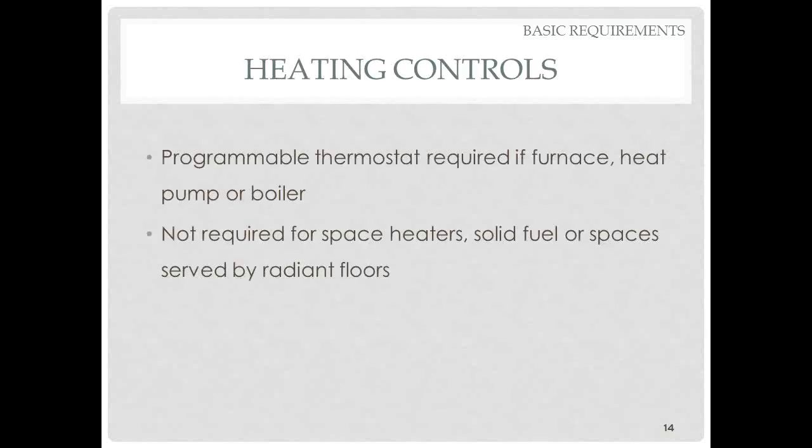A couple of requirements on heating controls. Basically, you now need a programmable thermostat for furnaces, heat pumps, and boilers that have convective baseboards. It's not required for boilers serving radiant floors or for zones that are radiant. It's not required for space heaters or for solid fuel.